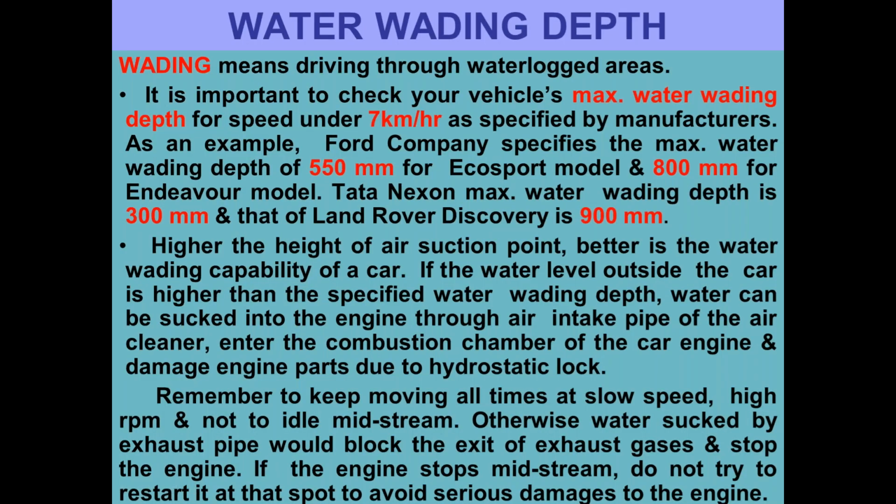Water wading depth. Wading means driving through waterlogged areas. It is important to check your vehicle's maximum water wading depth for speed under 7 km/h as specified by manufacturers. As an example, Ford specifies a maximum water wading depth of 550 mm for the EcoSport model and 800 mm for the Endeavour model. Tata Nexon's maximum water wading depth is 300 mm and that of Land Rover Discovery is 900 mm.